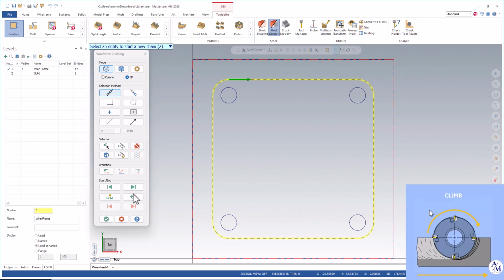So for example, if I'm moving this one to the other direction over here, if your selection is coming like this, it won't remove the surface from outside. It will remove it from inside because the tool will come inside and start rotating. So in order to remove something from outside, you need to make sure that your direction of chain should be in this way.